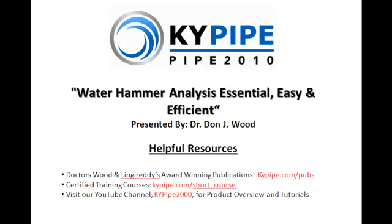Okay, this one is from Stephen Haynes. I completed an analysis of a fire water system, sudden electric pump start, and found hardly any difference in peak pressures when the static or jockey pump pressure was varied. Traditional fire engineering says keep static and service pressure close together to avoid surges. The model seemed to say static pressure is a moot point. Would you have expected this?